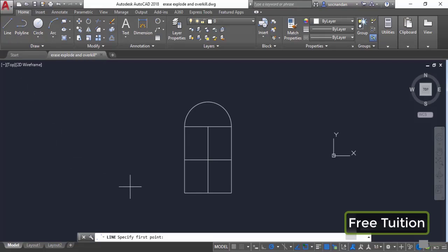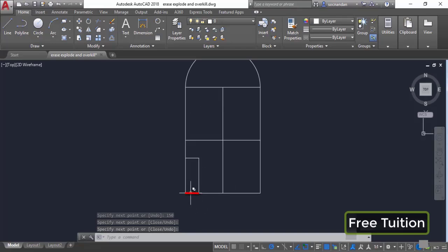For example, I've selected the line tool, and now I've clicked at this point, and now I need to take reference of that point, so that's why I click there. And now from that point I need to select a distance of, let's say, 60 units. So I'll type 60, press enter, and now I need to move upwards and I need to enter a distance of 150 units, press enter, and now I need to join it with this point.